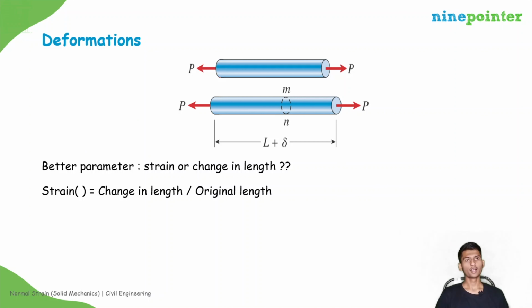If you take a bar which is subjected to a tensile axial load, what will this tensile load do? If you consider any two particles, it will try to stretch these particles away from each other, right? That is what we call deformations. But there is a bond between these two particles, because of which internal resistive forces are developed to resist these deformations, right? So deformations come first, then internal forces.